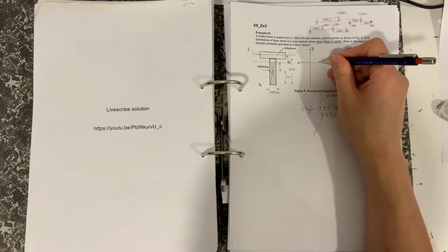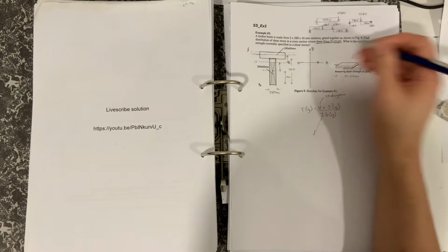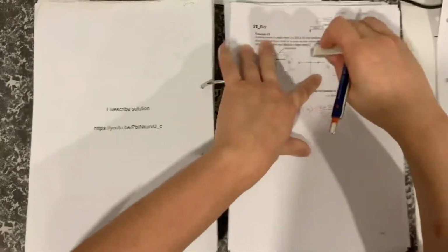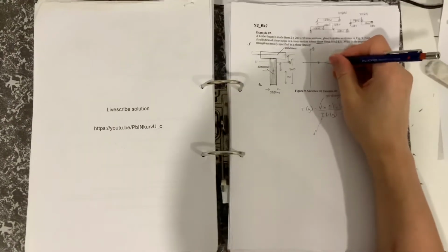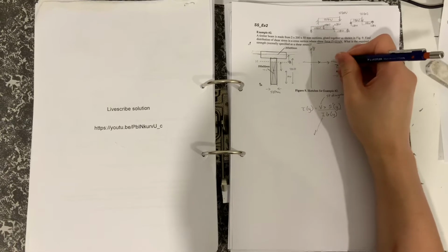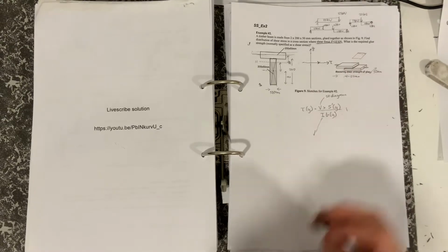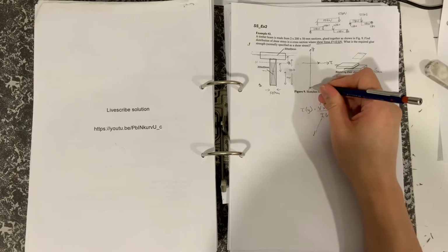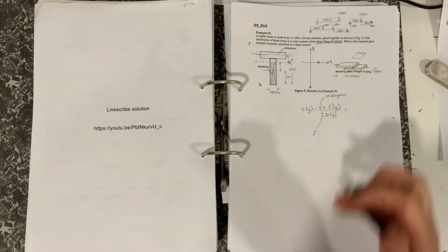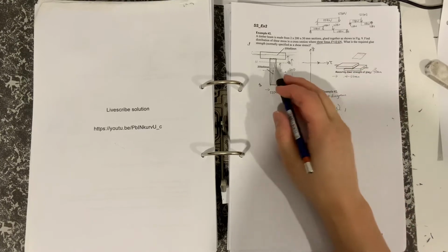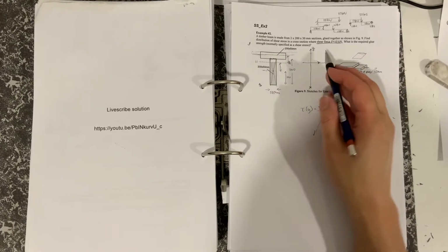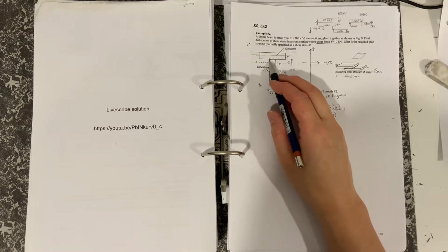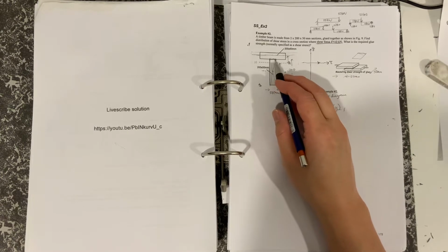So maybe we might get a value there. So I'll just get rid of NA since I've already described what NA is, and then I'll just put that as the shear that we're calculating. So the shear is going to be maximum at that value. The shear is going to be minimum at that value there. And as we've talked, you would expect there to be a jump or a step change above the glue and below the glue.